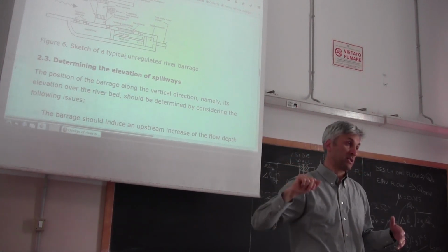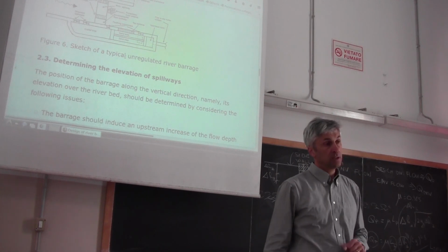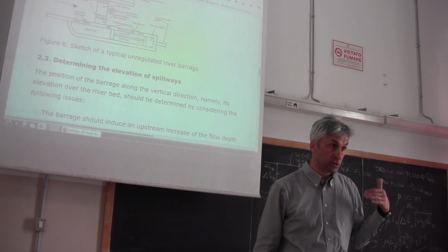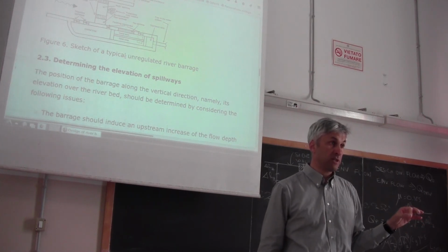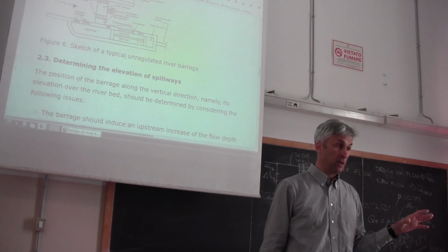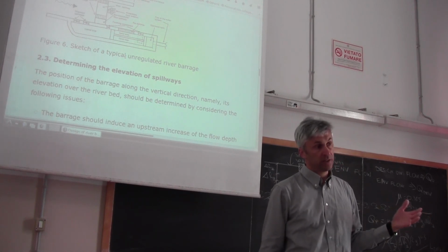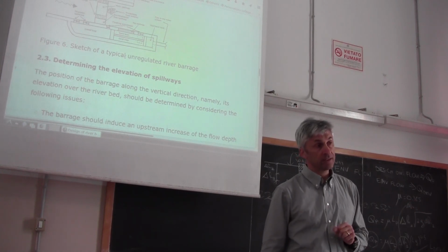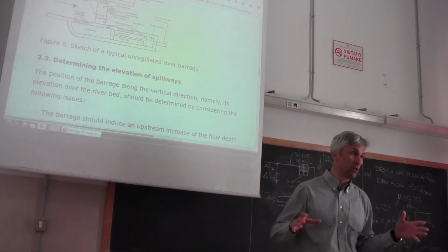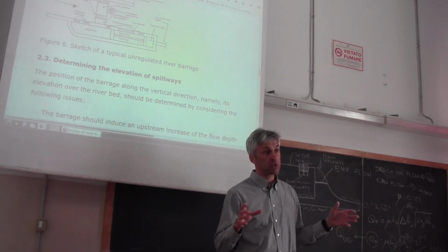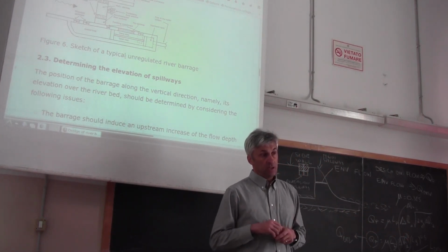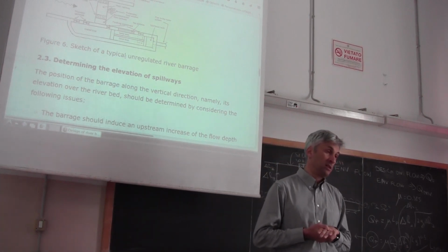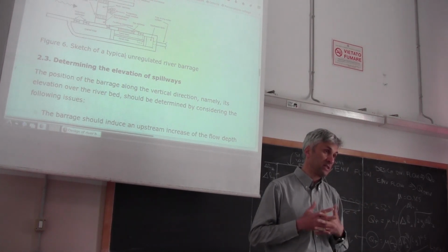And we usually place the gravel trap first, because, of course, the sediment that first settles down is the sediment of greater size. And therefore, we first remove the gravel and then we remove the sand. And usually the gravel trap and the sand trap are like two small tanks, two small storages. The sand trap usually is bigger than the gravel trap in terms of